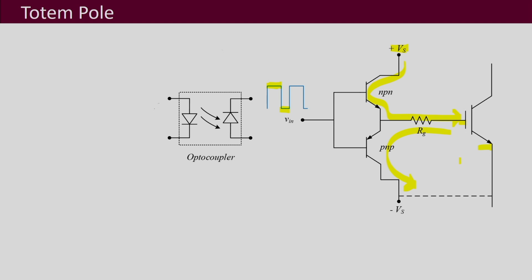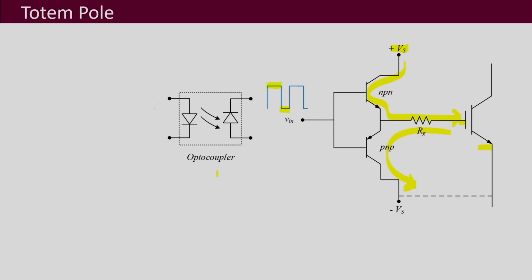So now we are able to meet the voltage and current requirements of the gate emitter or gate source region. So the first requirement of the driver is also met, and we also have the optical isolation. Another thing is the level shifting: over here your levels may be very small, let us say from 0 to 3.3 volt, and over here we may require something like plus 15 and minus 8 volt.